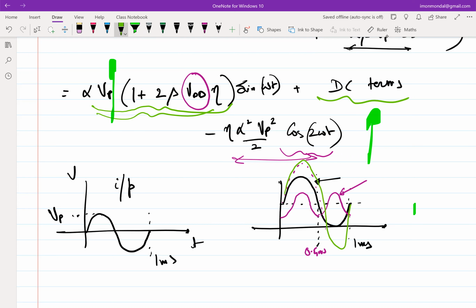What about the component with 2 omega? It will become 4x, right? So it looks like the distortion component, the undesired frequency component, is running faster than my desired frequency component if I increase the input amplitude. That is happening because it should not surprise us, because I have squared.